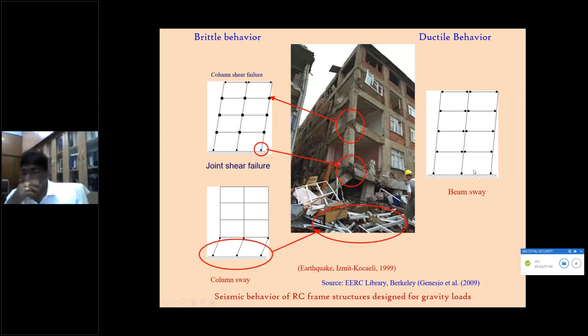That is the case. In the beams, if at all, plastic hinges will form locally. Formation of a plastic hinge means yielding of the reinforcement in the beam. That is allowed so that you will have sufficient warning. Therefore, the capacity of the beams can be achieved before the capacity of the columns and joints is reached. So your design will become more ductile, with local failure in the beam and no failure in the vertical system. No failure in the joint, no failure in the column. So that's what we actually have to do.